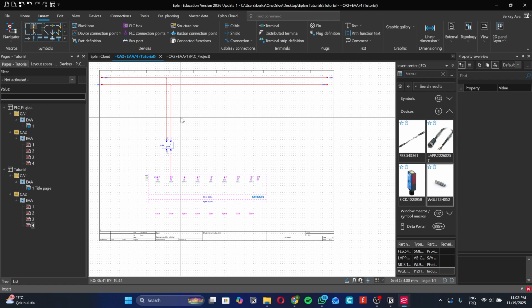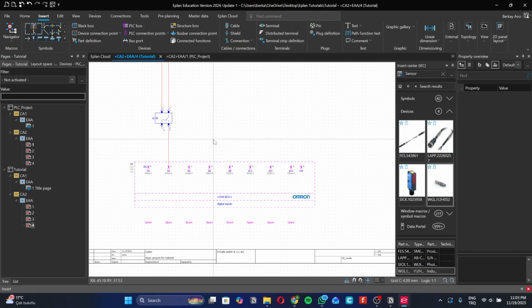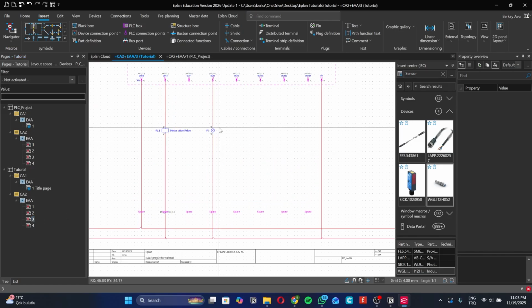We had an induction sensor like this. If the metal plate going through the band gets stuck and we read signal for more than 5 seconds, then it was turning on the alarm. The light here starts to turn on and off, like blink.